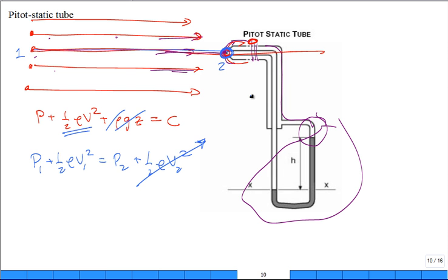Guess what, that dynamic pressure, it comes by different names, it's 0 at the tip. All right? And so now you say, this allows me to know what is 1/2 rho v1 squared. What's that free stream velocity? Well, it's the same as right here. This one's going this way. There's such a small difference in the length, there's no real pressure drop between the tip and the back. And so this static pressure on the outside is equal to P1, is equal to the static pressure.